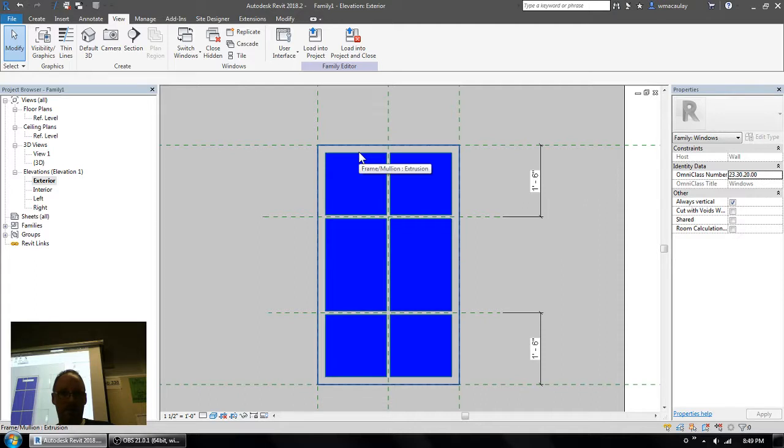Okay, so what I'm going to do is put my cursor on the frame. Now have a look at what's on the cursor here. When I move my cursor around, it may choose the glass. No, it's not. I'd have to probably tab select to get the glass. Yeah. So when I put my cursor over these different solids in my window, what I want to do is go back and edit my frame sketch so I can see those pink lines again.